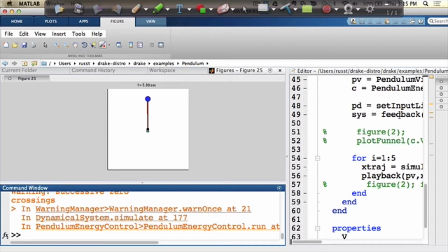Your LQR gains might be asking for a lot of torque, let's say over by the origin, and your energy controller is actually trying to give just a little bit of torque. So it might actually be non-trivial to mix those in a good way, right? Yeah, I think that would be the number one problem, especially if the LQR controller is not necessarily good at thinking about all the wrapping issues. The nonlinear controller, just by having the sine and cosines inside the equations, actually handles all the wrapping of the coordinates very nicely. So I think that's probably the number one reason. But you're right, the complexity of switching is this extra logic of being a switched system that we'll talk more about later. And that's a pain.